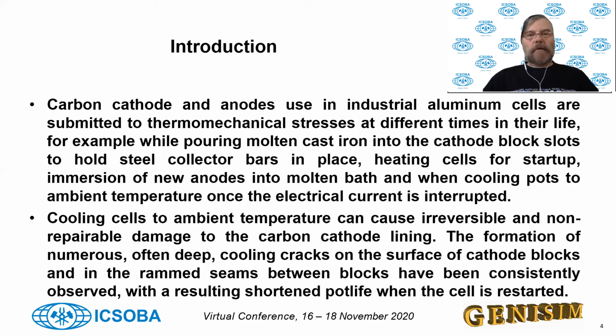there's some stress occurring in the cathode, and if the power shutdown lasts too long, you will get some cooling cracks, especially if you bring the pot to ambient temperature and then later on you restart. You will see that there's some cathode damage, cooling cracks, that are unrepairable, and they will have an effect on the ultimate pot life of the potline.